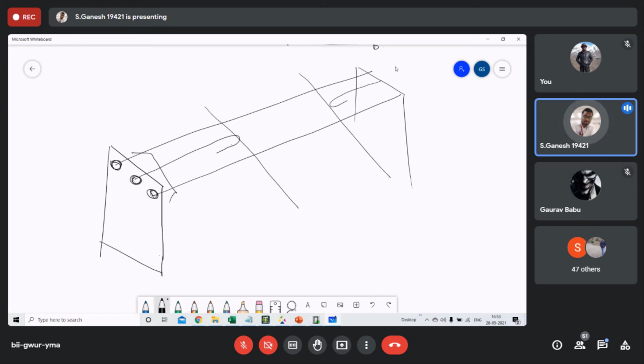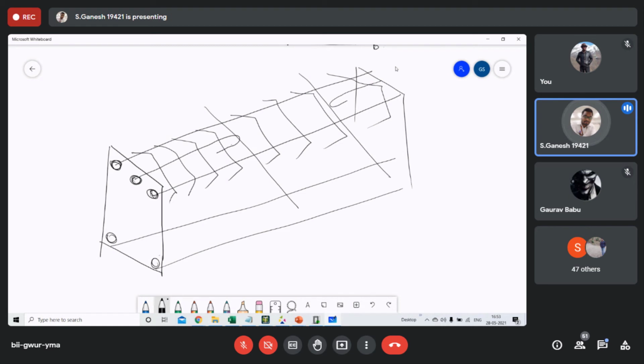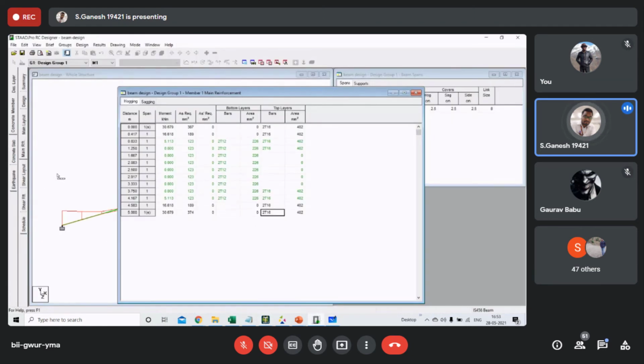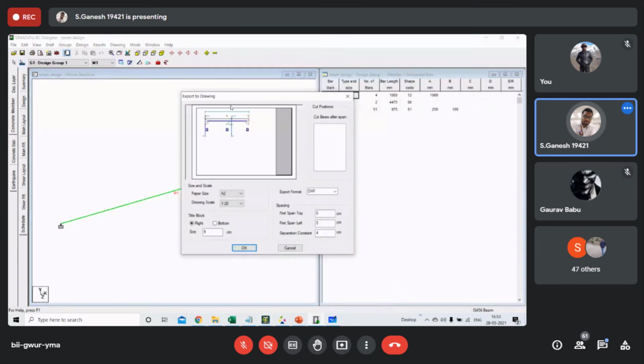Then we make the stirrups, tie with the stirrups, and take care of the stirrup spacings, and in the middle we have stirrup spacings. Like this we make a design. And at the bottom, suppose 2 bars are running throughout. This is what we do in RCC design, what you see in the CAD diagram, which the draftsman used to do. So finally we get your designs on the screen. You can see these diagrams also. These bars are exported to a DXF file, and you can open and see them in your drawings. So that completes your RCC design.